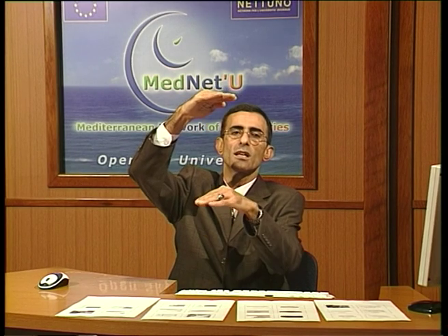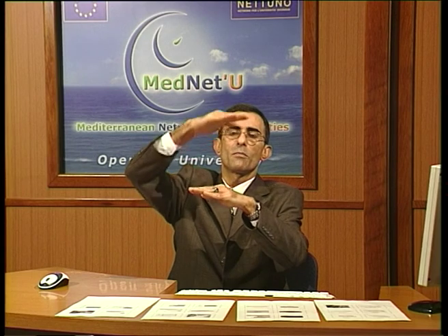So this incompressibility of the fluid will make sure that it's like a reaction force. It's like this mass of fluid is exerting a pressure by its weight on the layer beneath it, and the layer beneath it is exerting a force in the upper direction as a consequence.